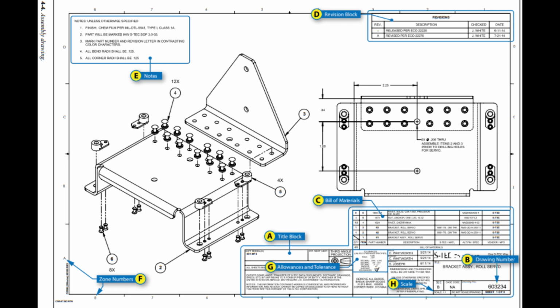Reference and dash numbers. Reference numbers that appear in the title block refer you to the numbers of other prints. When more than one detail is shown on a drawing, dash numbers are used. Both parts would have the same drawing number plus an individual number, such as 40267-1 and 40267-2. In addition to appearing in the title block, dash numbers may appear on the face of the drawing near the parts they identify. Dash numbers are also used to identify right-hand and left-hand parts.